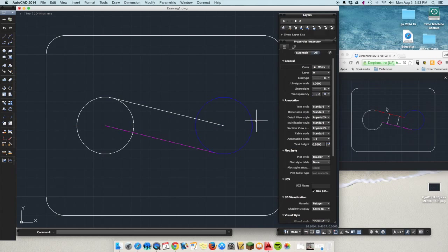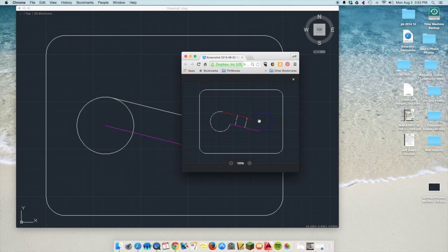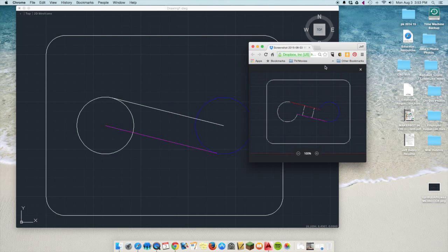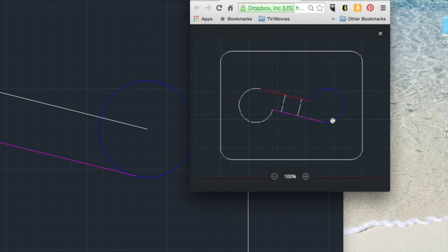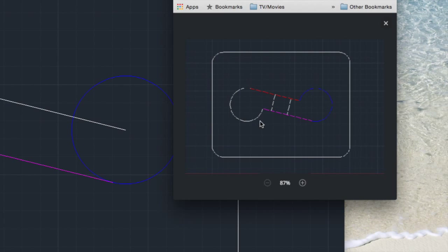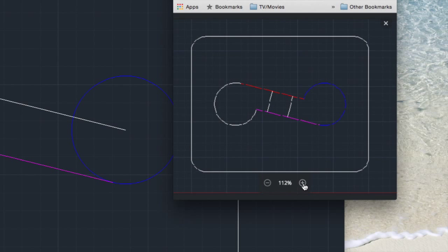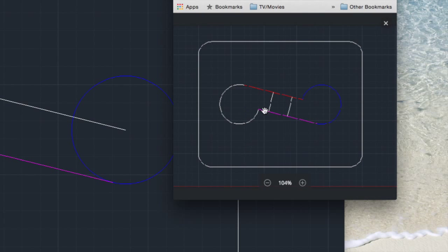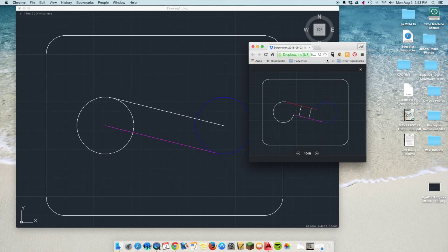Okay, so the problem is, if you look in this drawing, the lines, except for it's looking a little funky. Whoops. The lines should look like solid lines. I don't know why it's looking a little bit broken. The lines don't continue to the center of the circle. They get cut off where the circle meets it. So that's called trimming. So we're going to do some trimming.